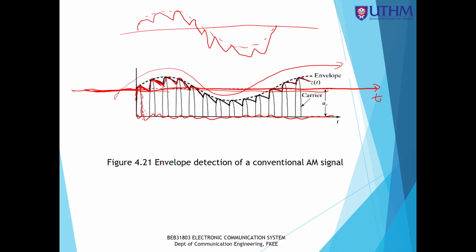The signal will go down to the x-axis, so it will start at 0 volt. Previously, the signal starts at DC voltage. Now the signal starts at 0 volt because the C2 capacitor removes the DC voltage.